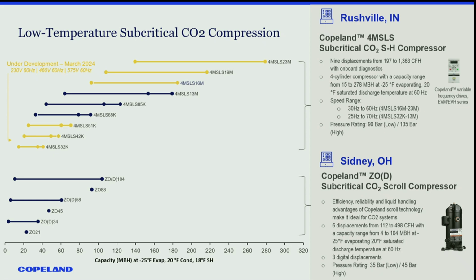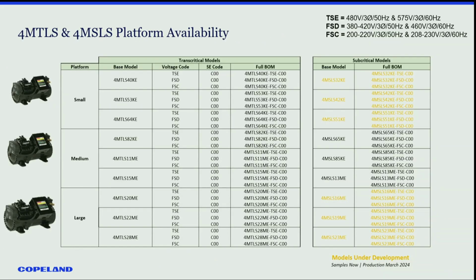And we also are launching the low temperature, high standstill version. Remember I talked about how some customers want higher standstill pressures, so that low temp compressor has got to be able to handle 1,305 pounds when the system is off. So we have those in a semi-hermetic version, also made in Rushville, Indiana, and scrolls. They've been around since 2009, from 21,000 up to about 100,000 BTUs, just to give you an idea. And you'll get PDFs of these presentations; the NASRC makes everything available. So these are just the model numbers and the various voltages that we have: 460, 230, and 575.